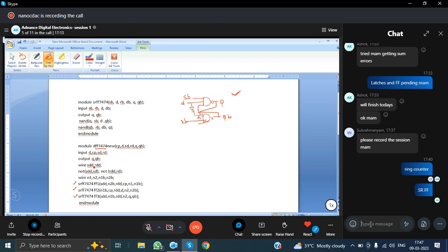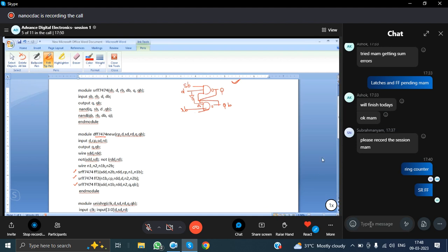See, why do we use the D flip-flop everywhere? In sequential state machines, Mealy circuits or Moore circuits, if you want to synthesize any design, you will go with the D flip-flop, because you can easily realize it using the D flip-flop. Why? Because it is easy to understand. There is no toggling in the D flip-flop, and unlike JK, there is no race around condition. It is easy to realize, and I also told you there is the concept of scan chain by using D flip-flops.